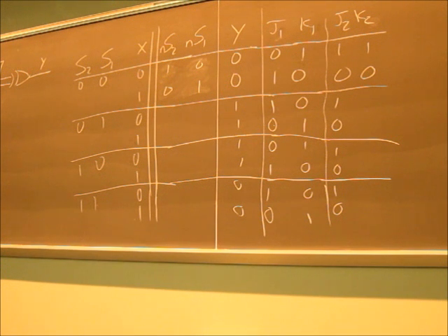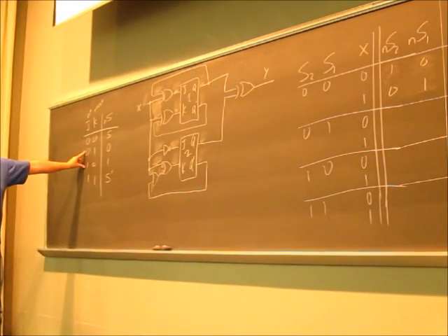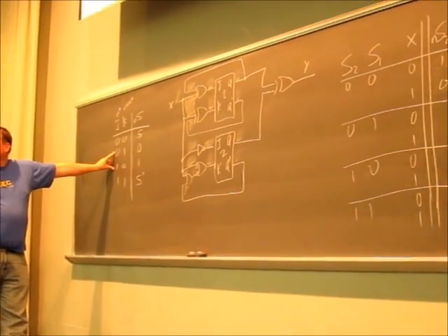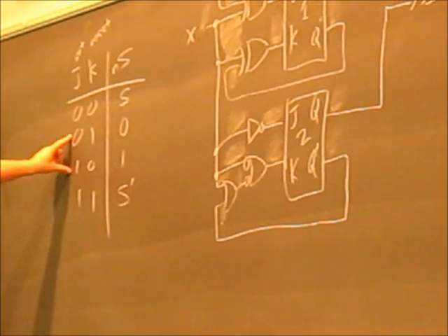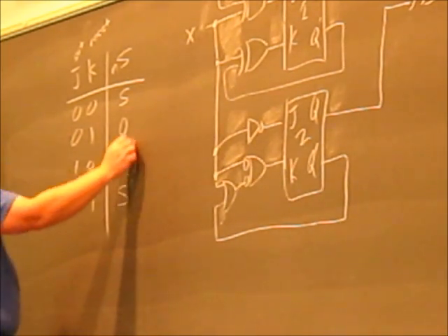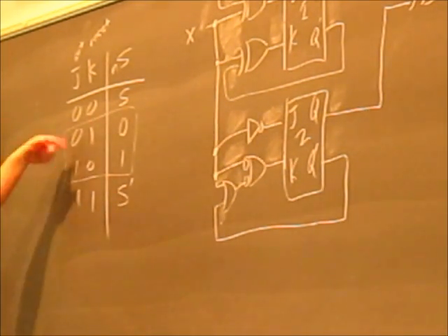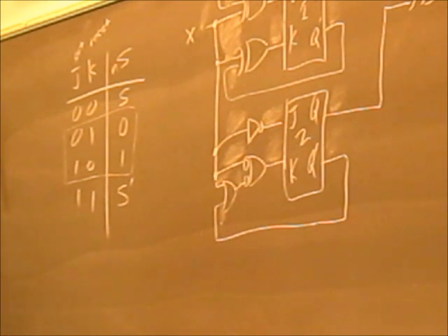Now think about what that does. It's always a 1 or a 2. That's the inputs, the JK, right? JK is either 0, 1, a 1, or it's 1, 0, a 2. Which means I'm right here in the middle. What did I turn that first flip-flop into? It's a D flip-flop on whatever's coming in on your J line.